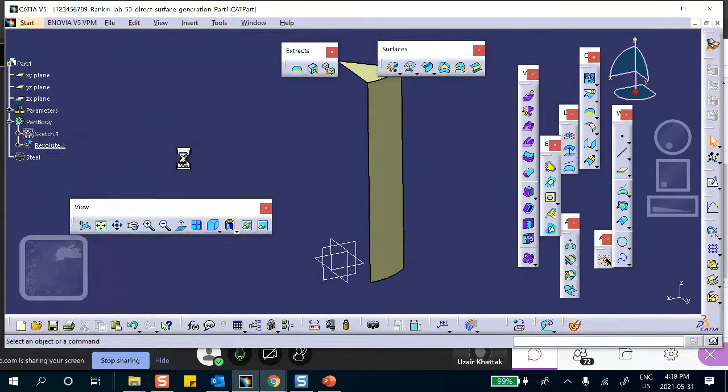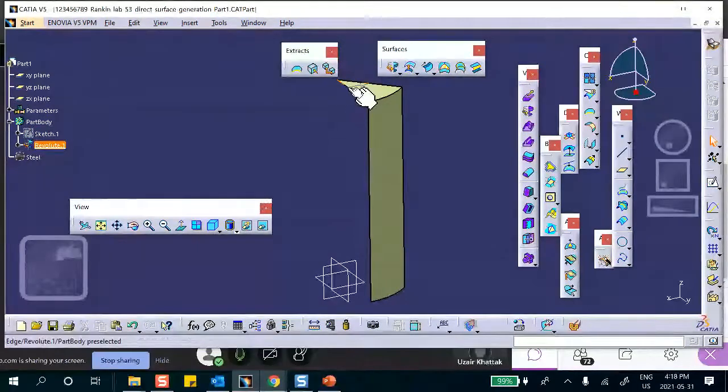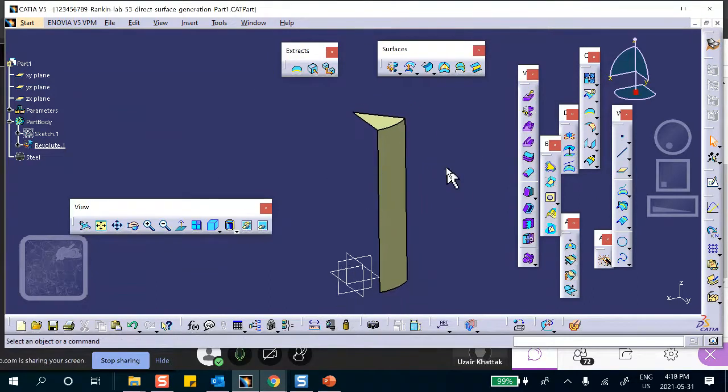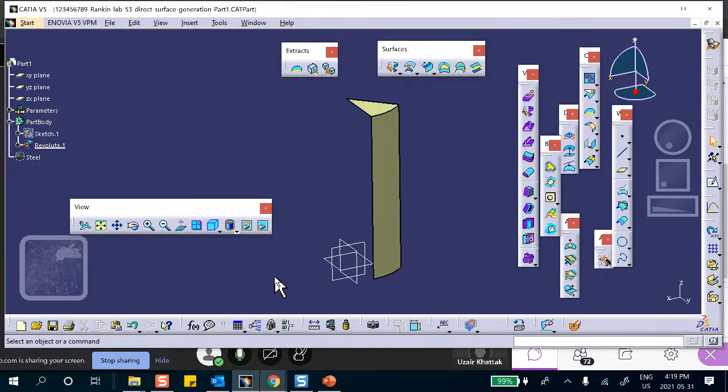Hide. Once again, I want to remind you, that sketch that I just hid was in the YZ plane. So when it comes to symmetry, I have no problem. I say no displacement in global X because it was in the YZ direction, and the same type of thing for rotation. But these two other edges, because I took 45 degrees, will not lie in the YZ plane or XZ plane, etc. If I had taken 90, by the way, it would have been in the XZ plane. But I said I'm going to make your life harder. Okay?